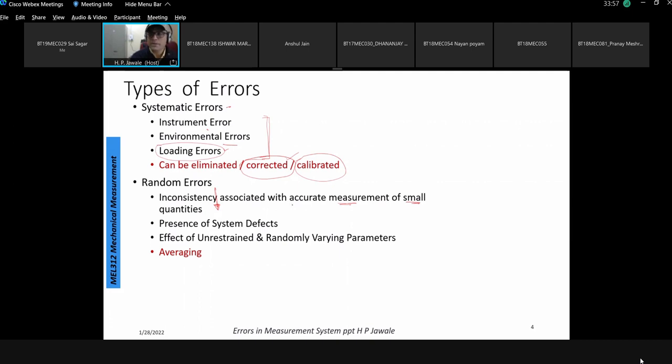Right. There are many defects which may be present in the instrument or measurement system. For example, there are connections and electric circuits which have some temperature sensitivity. During usage, the temperature of the resistors, capacitors or other elements builds up, and because of that, slowly more and more output is shown for the same input given. Or, for example, there can be deflection in the scales.